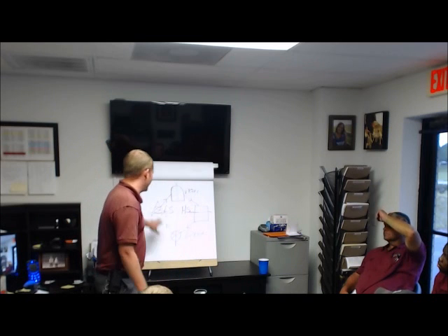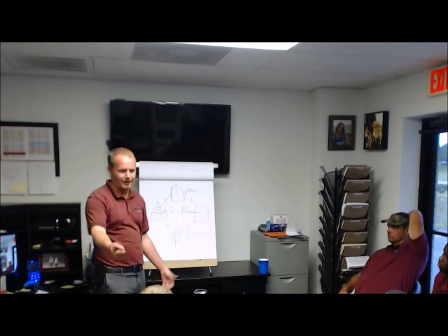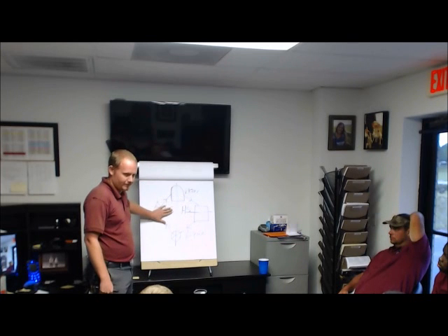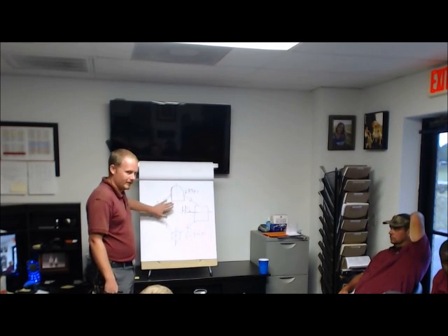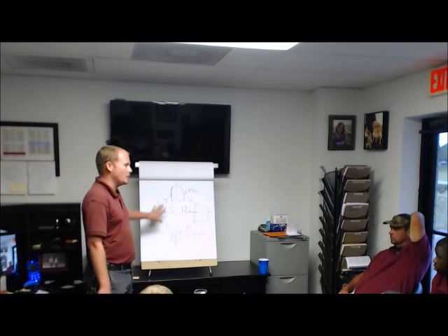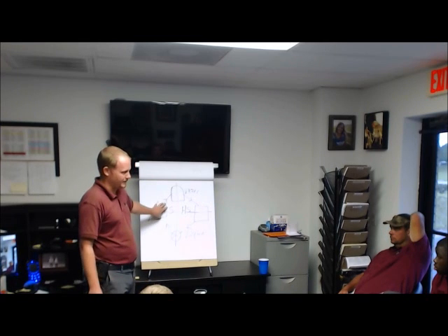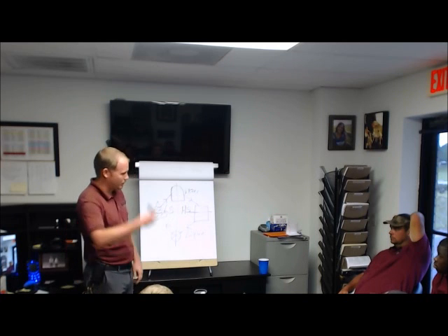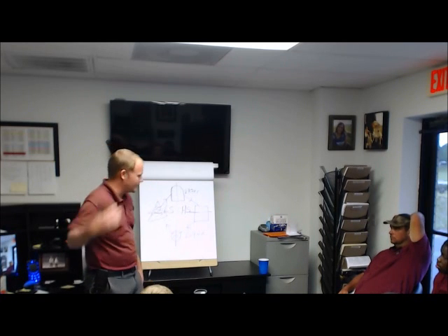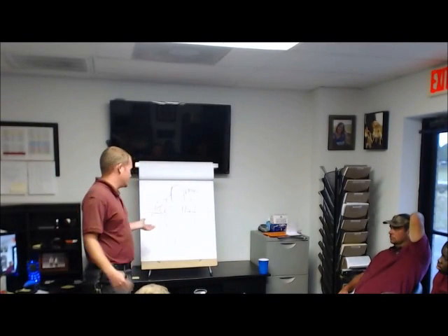Think of this evaporator coil. I know it's counterintuitive because the stove's hot and it's boiling, but it is. This is a big boiling pot of water. Okay, and we want to boil off this water. If you throw cat hair on it, you've turned down the stove because you're now exposing that to less heat than you would have in the first place. Because remember, all that air that's going across that coil, that's giving it heat. That's the flame underneath the boiling pot of water. Okay, you reduce that, now you're not exposing it to as much.